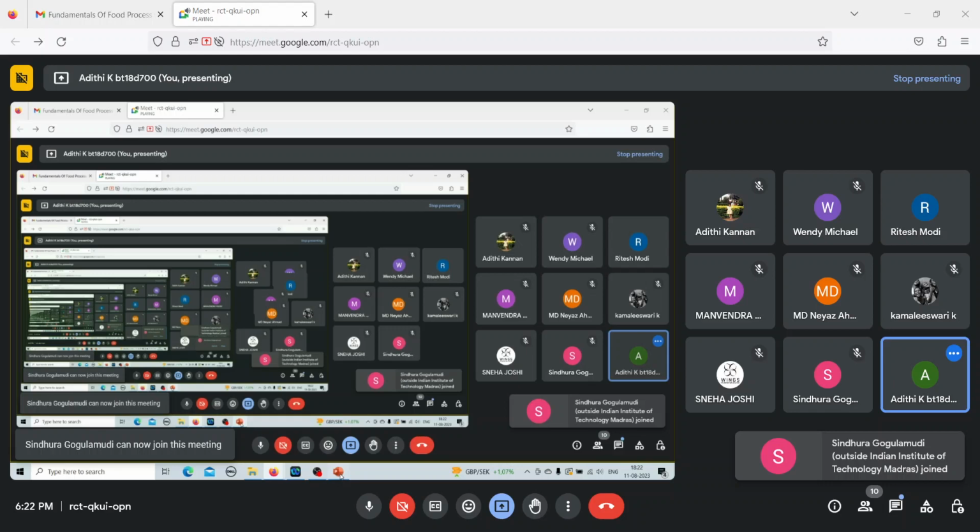able to reduce the microorganisms from 100 to 50. It's just a random example I'm giving. At 130 degrees Celsius, within 1 minute, I am able to reduce the microorganisms from 100 to 50. So the same 100 to 50, how much time is it taking at 121 degrees Celsius is known as the lethality factor. I hope this is clear. So the moment you talk about time at 121 degrees Celsius, it is automatically F naught value.